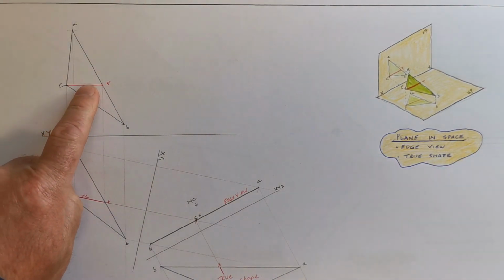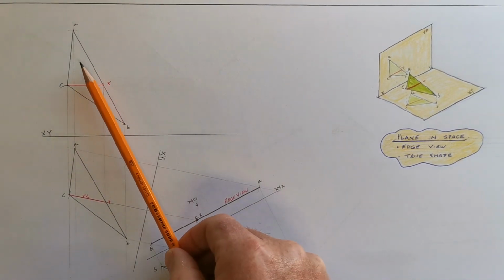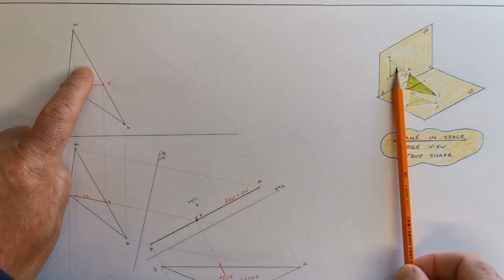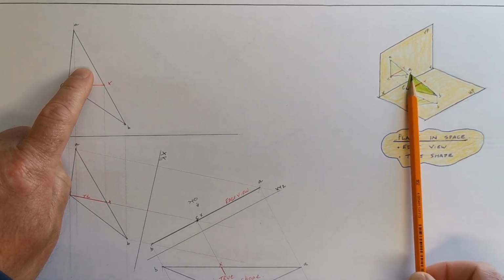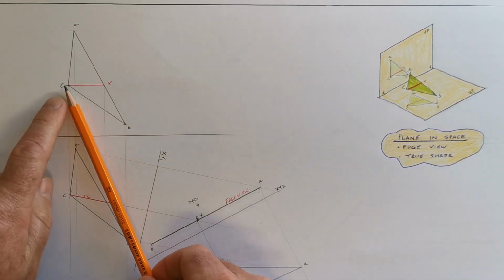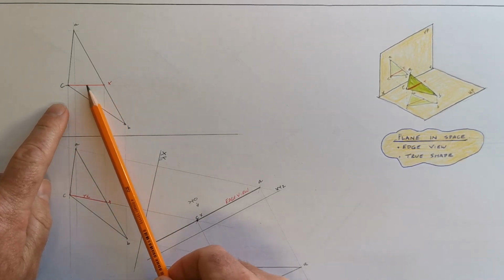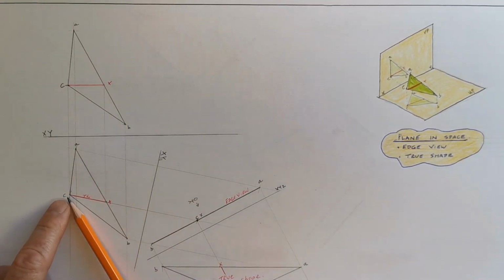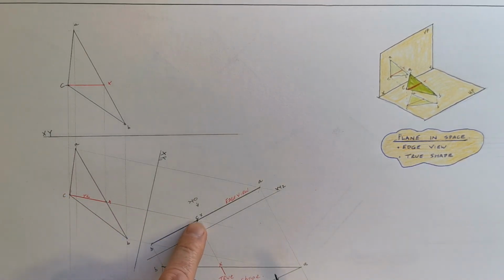So that's some of the most basic stuff to understand there, how that's a projection of the plane that's suspended in the air, and that basic system or rules of taking a horizontal line in elevation, getting that horizontal line in plan, and looking along it to find a point view.